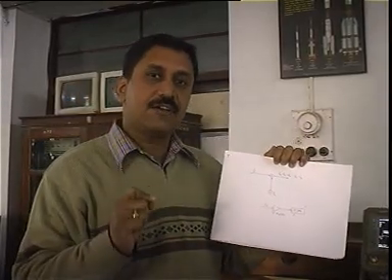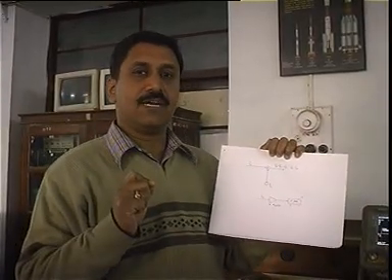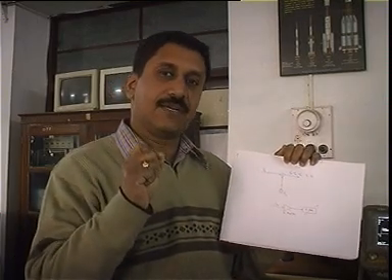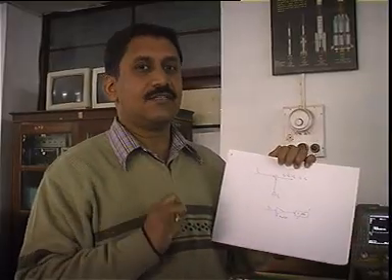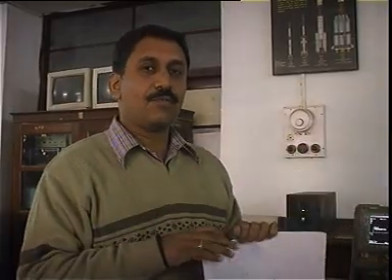So sensitivity of the instrument is measured at the minimum resolution bandwidth, the tiniest, the smallest power that the instrument can measure at the smallest resolution bandwidth available in the instrument. So these are the three important specifications of the instrument you must keep in mind if you want to order a spectrum analyzer or if you want to work with a spectrum analyzer. Okay, so these are some of the things you need to keep in mind when we go with the demonstrations